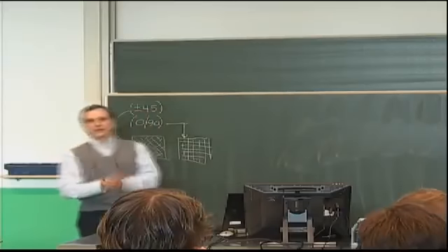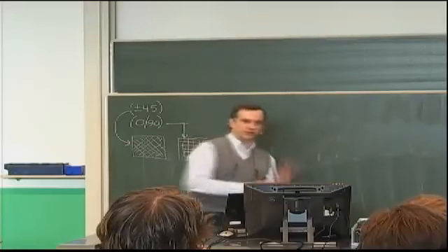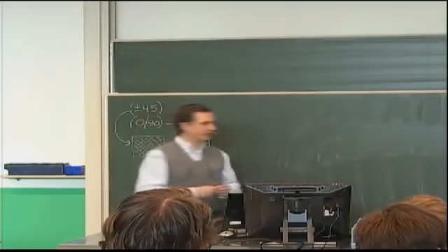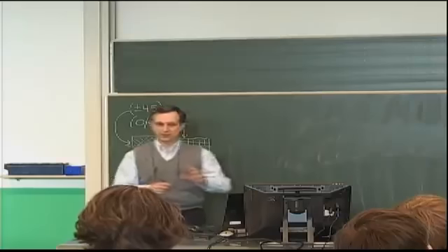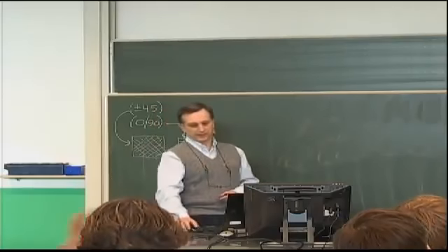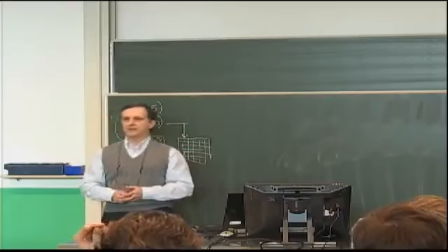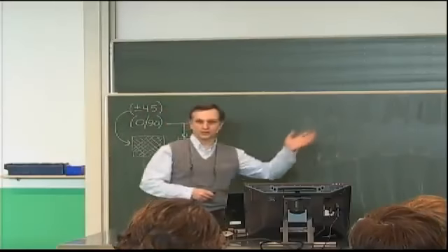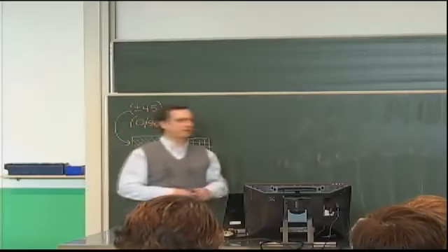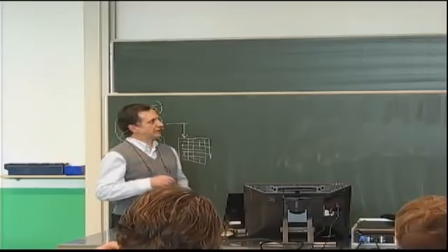So on the one hand, we have a warm enough feeling at this point that our solution is good because it's close, if not very close, to finite element results. And on the other, we think that by looking at what regions along x or y the stresses are appreciable, we can determine the regions that would need to be reinforced. So now we open up our design space, let's say, and we try different laminates. And to run this now with the solution we have would take seconds instead of hours by the time you set up the finite element model.